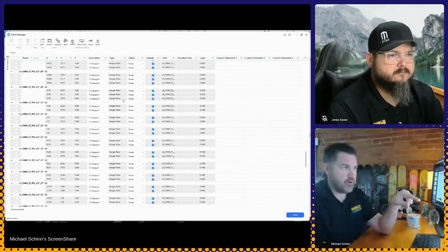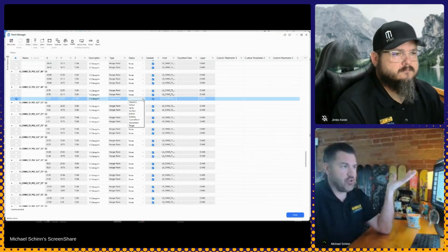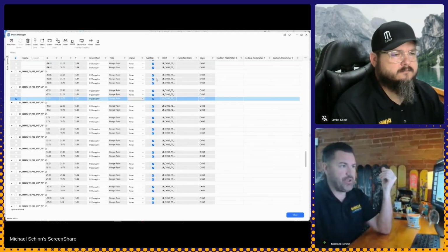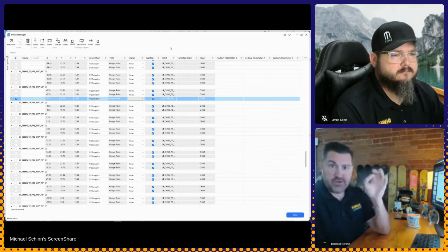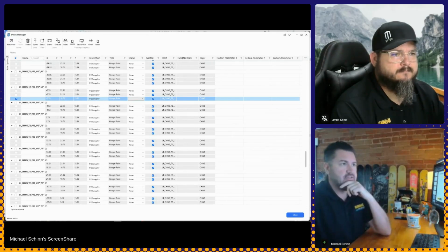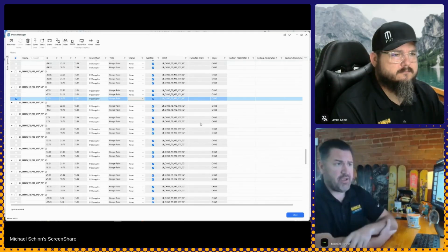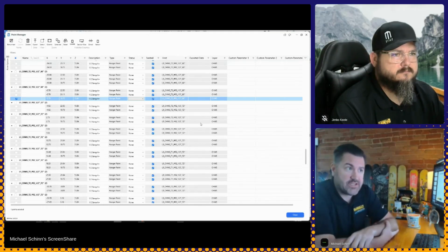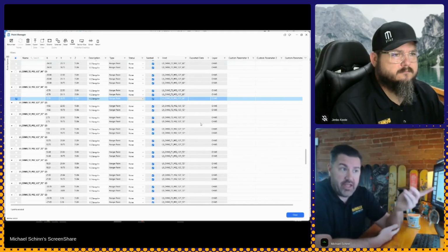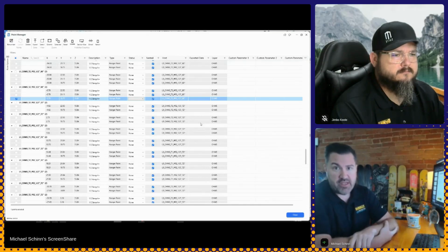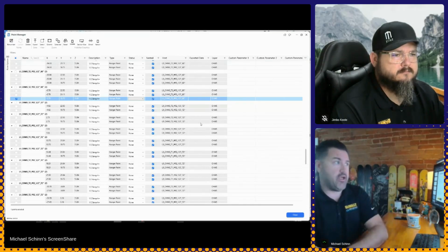It automatically defaults to a hanger point. I have full control of controlling what the status is of that point. We do handle also nesting our family point inside of any of your own custom families. The host is just describing what the actual family or hanger name that's inside of. Export date, that gets filled in automatically when you export these points. The layer automatically fills in the system abbreviation associated to that element.